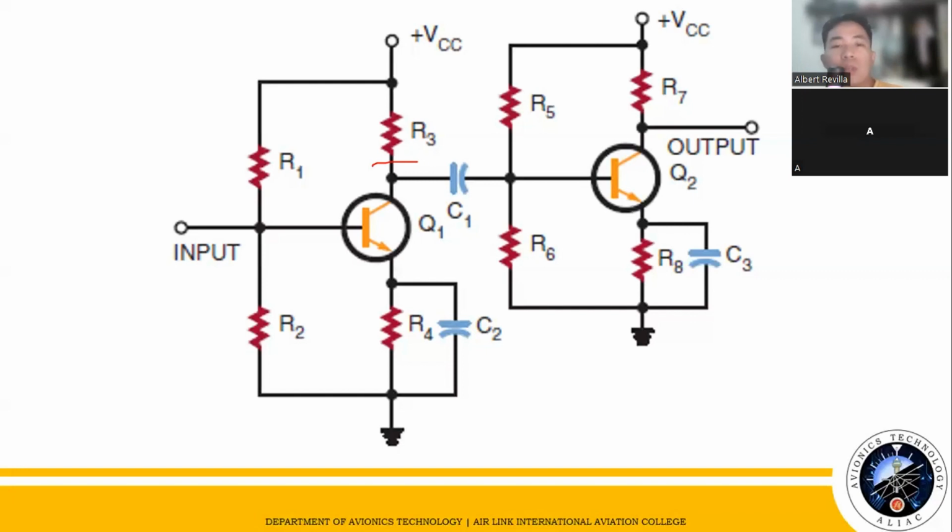And the capacitor C1, this one, is the DC blocking and AC coupling capacitor. So, resistor R5 and R6 are the input load resistor and DC return resistor for the base emitter junction of the second stage. So, resistance capacitive coupling is used primarily in audio amplifier.